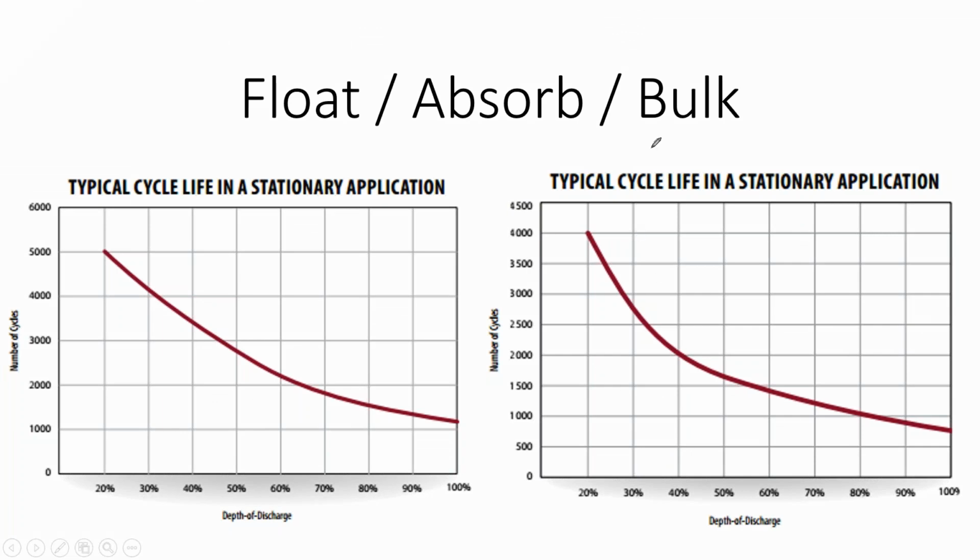And so if we went with this mid-range premium battery, it could easily take a daily cycle of right down to 35%, but not much more than that. At 35% depth of discharge, I'm getting about 2,200 cycles out of it. Our battery bank is 105 kilowatt hours, and 35% of that is about 38 kilowatt hours.